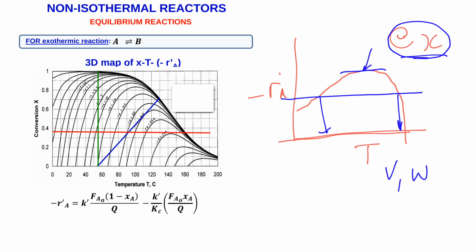So I left all these beautiful views of the high cliffs and the very high rates that I could utilize unused, and I jump immediately to this very low value close to the beach. So it's often not a good idea to jump in a CSTR to a very high conversion value, even though you optimize at that single conversion value by targeting the maximum in the rate.